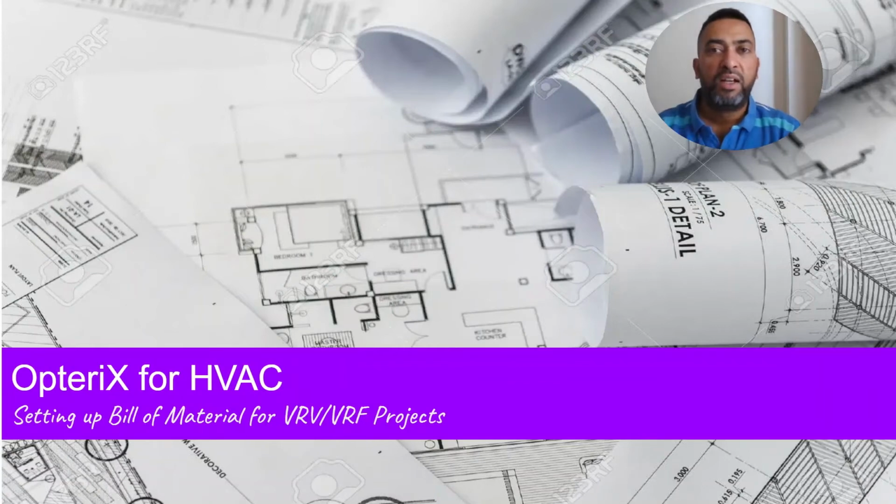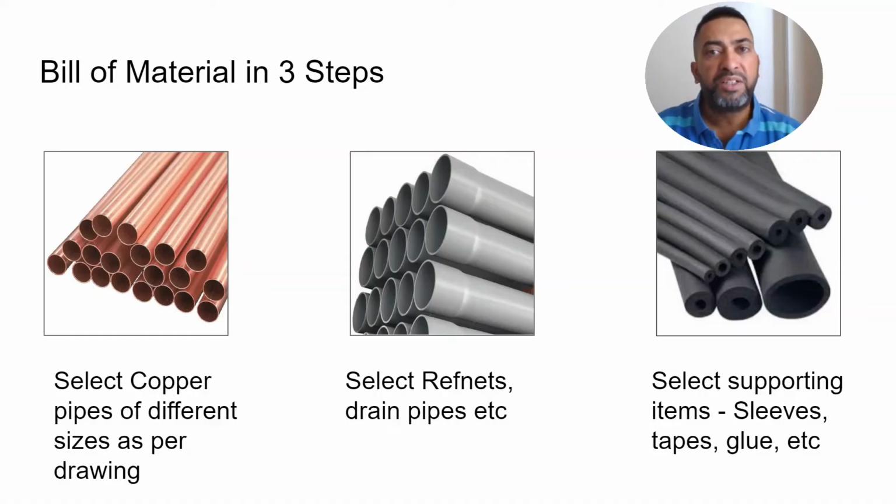Hello. OpteriX for HVAC has made it easier than before to set up the bill of material for VRF and VRV systems especially. It's done in three simple steps. First, you select the copper pipes of different sizes as per the drawing. The next step is to select the ref net joints, the drain pipes, etc. This is a semi-automatic process. And the third, which is a fully automatic process, is a selection of all the supporting items, the tapes and the glues and the sleeves, etc.